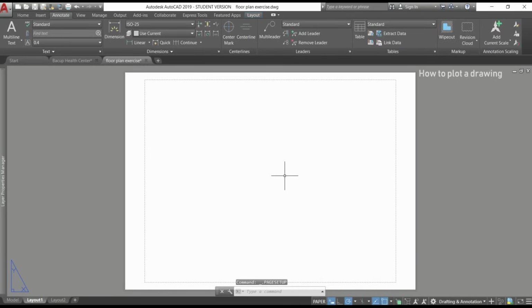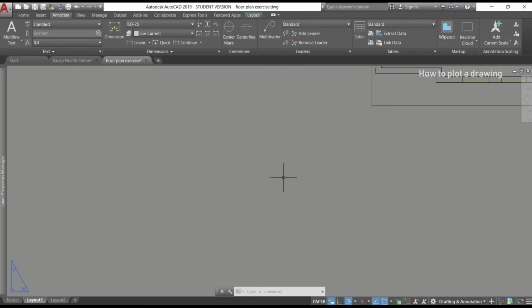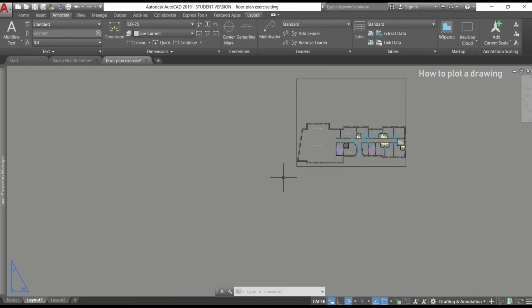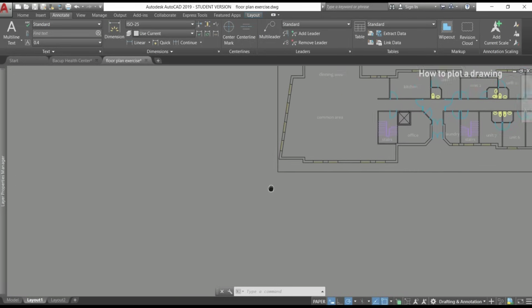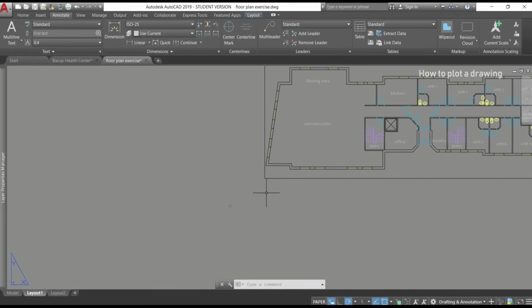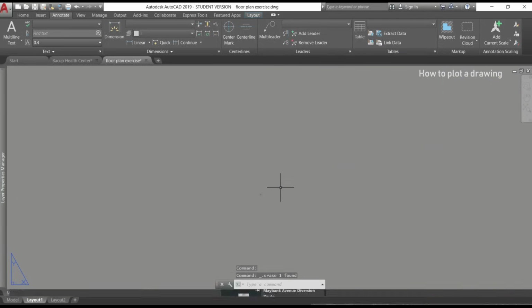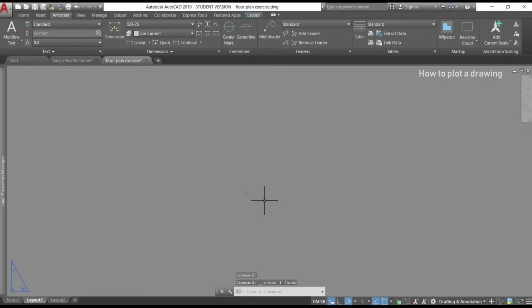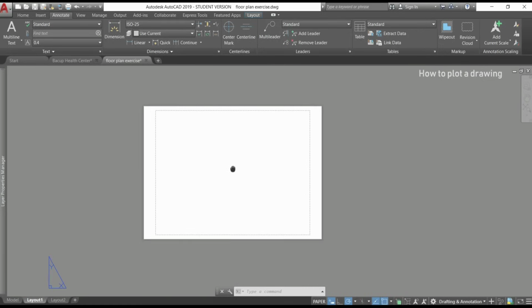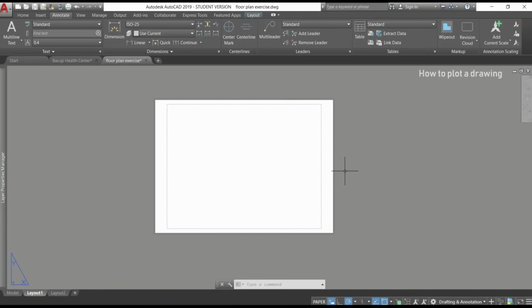As you see, the viewport disappeared. Apparently, of course, because what happened is that the paper was resized, but not the viewport, and if I zoom out a lot, I can see it very big outside. But don't worry, the first thing is to click there and delete it. In fact, I could do it before resizing the paper. Now I zoom in again, and let's create a new viewport.